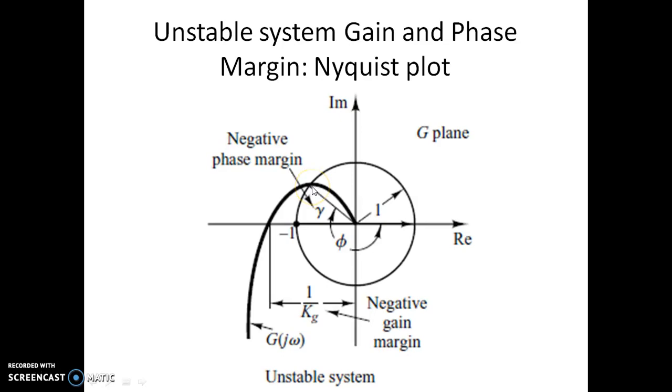When it is minus 220, the phase margin is 180 minus of this, which is negative now. And this is the gain margin: since the magnitude is more than 1, the gain margin is negative. In terms of dB, this will be a negative gain margin.